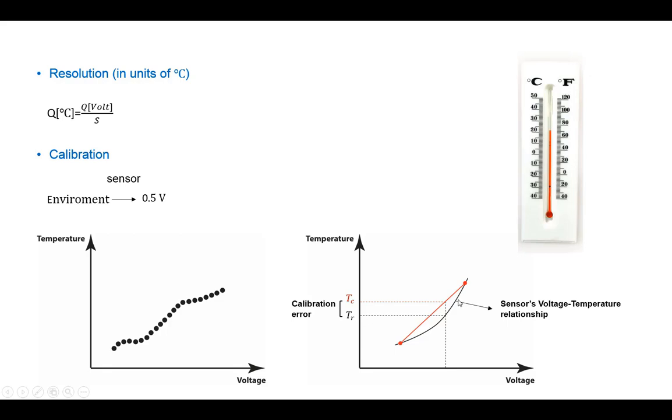What I'm going to do is consider just 2 points. I measure the temperature at one specific ambient and also measure the voltage my sensor is producing at that ambient. Again, I do the measurement with that sensor in a new ambient with a new temperature, also measuring the voltage of the sensor there, and connecting these 2 points to each other, obtaining a line, then giving this line to the computer.